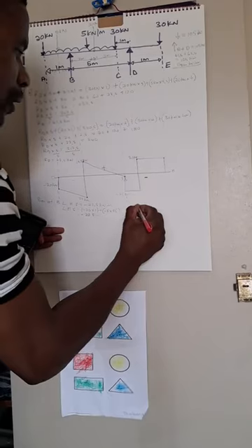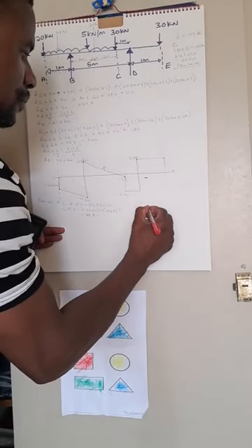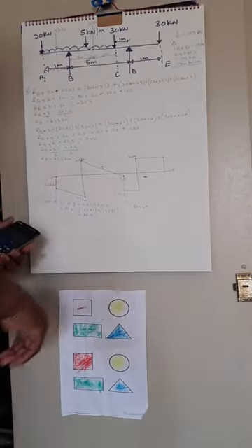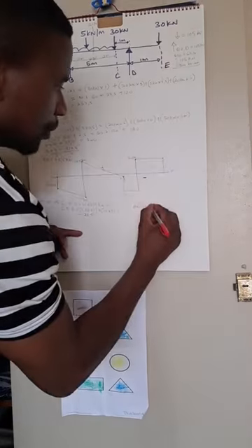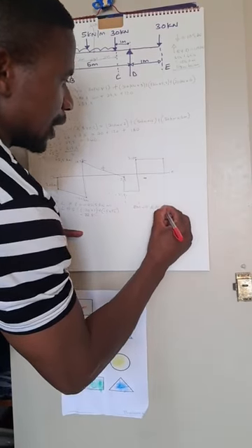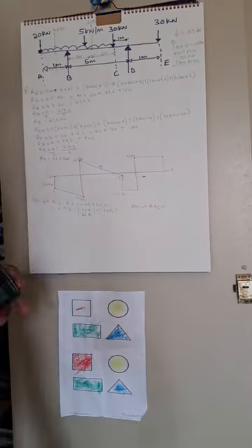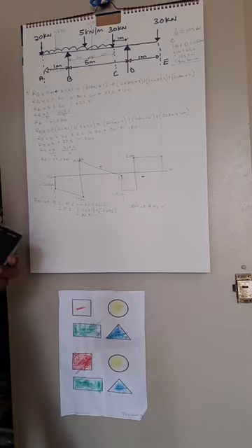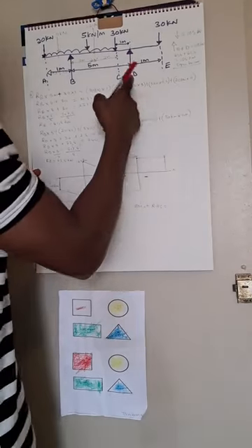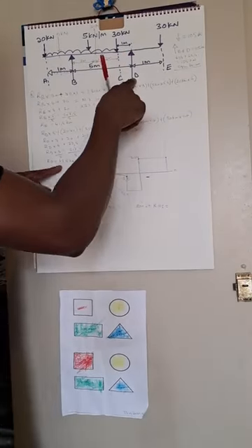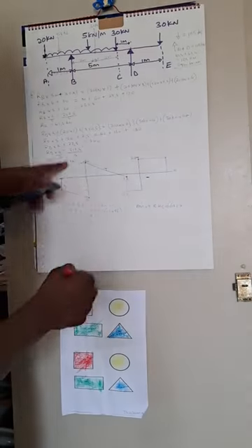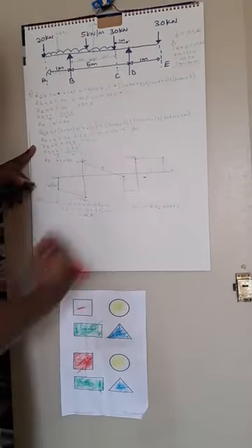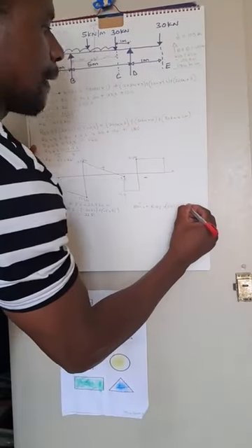Now let's calculate our bending moments at C. If the one bending moments at C, there's no problem, we can do that one. But the easier way, we can use the right hand side. Now, if you calculate bending moments at C from the right hand side, you can start off by your positive 63.5 times the distance to C, which is 1 meter, minus.